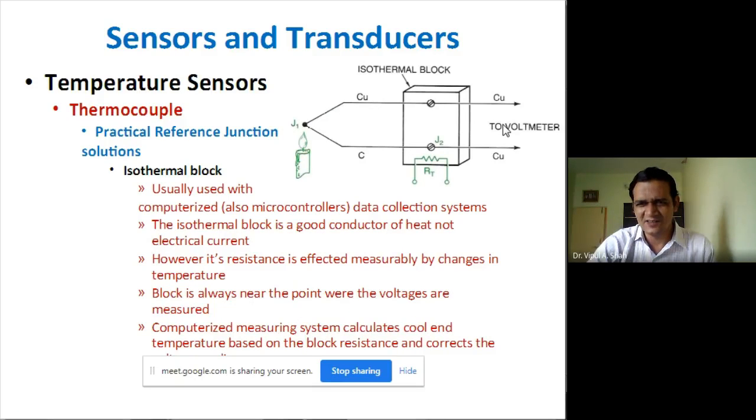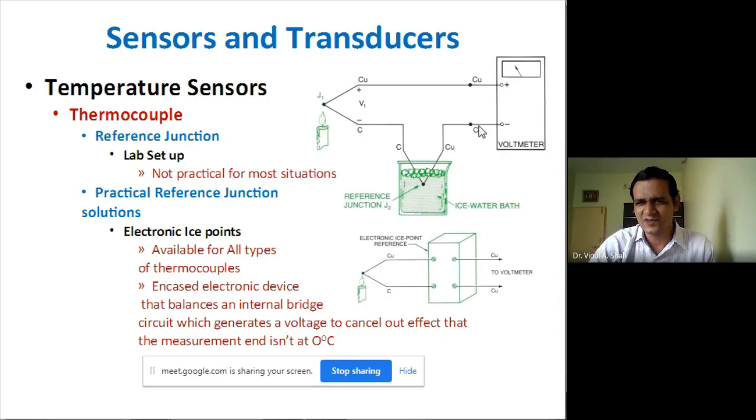Now as and when the thermocouple gives you the output, you should carry it to the remote location also. So for that remote location transfer, we are utilizing the reference wire, which is normally a manganin wire. So suppose there is a distance of around 20 meters between your specific point, which is a measurement point, and your control room here, then you should have that wire extension.